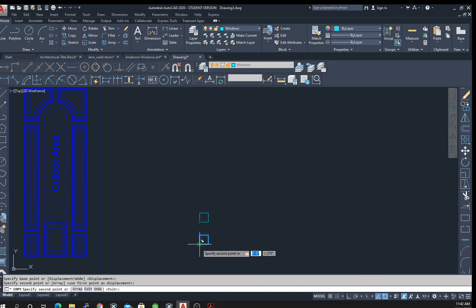So if we're starting from here, we want to make a 5-foot window, we want to make it actually 7 inches shorter, because this block will extend by 5 inches. Excuse me, we want to make it 5 inches shorter. So we're going to make it 4'7". So we're going to type 4 feet, 7 inches.